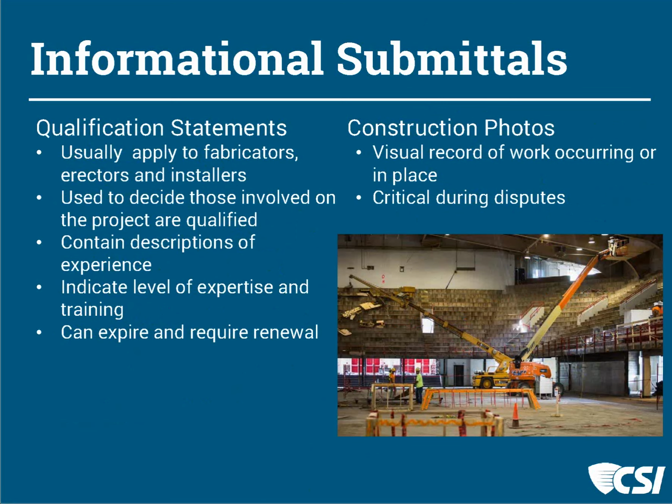Well, I think that the intent of an informational submittal, first of all, should be very well described in your general conditions or your supplementary general conditions, to say this is an informational submittal only, that we are not taking an action on it, but they are being shared with us for information purposes only.